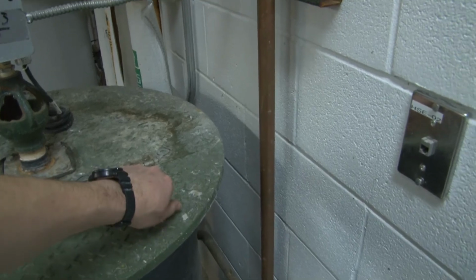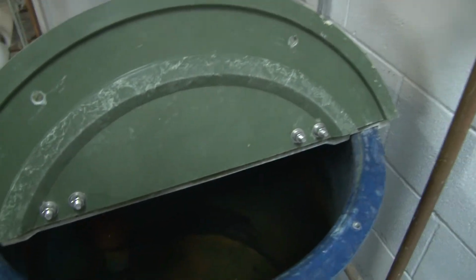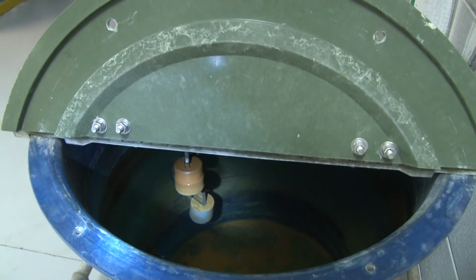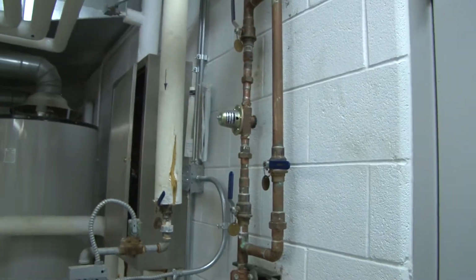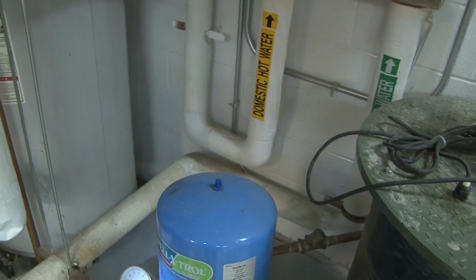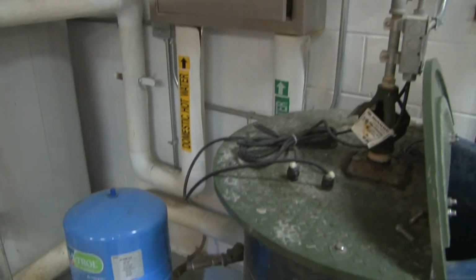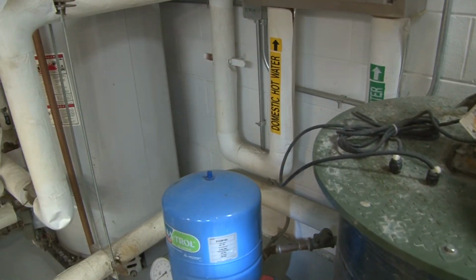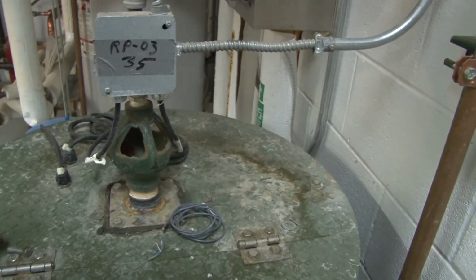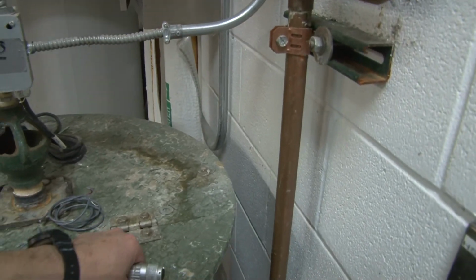And then let's see what we have here. This tank will allow water to be in reserve, and we have floats right there that, when the water goes down for whatever reason, will allow water to go in through that valve and maintain a level. And then when the pressure in the system comes down due to a leak or another reason, the pump will sense that differential in pressure and operate and inject water and keep the designed pressure at the correct number to allow the water to flow in the closed loop at the correct flows.